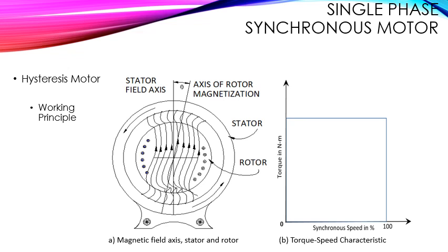The hysteresis torque due to the interaction between stator and rotor field is proportional to the product of stator flux, rotor flux, and the sine of the hysteresis angle theta.